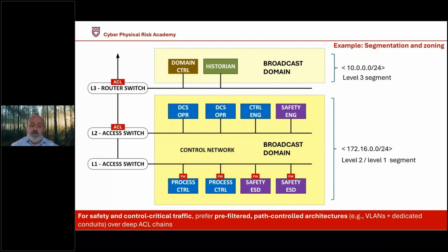And that happens a lot, certainly when you have a big plant with many places where you have controllers, multiple control rooms, multiple equipment rooms. There is a lot of traffic going on there. So there have always been people that say, okay, let's put a big firewall there, maybe between level 2 and level 1, or a firewall between the safety part and the process control part. Well, if you do that, you reduce the speed and the performance of all traffic.